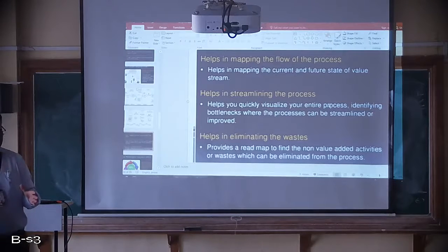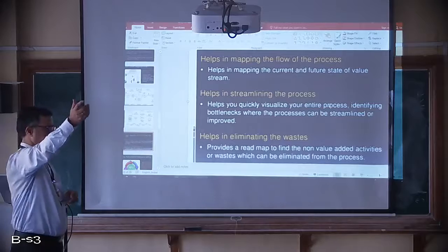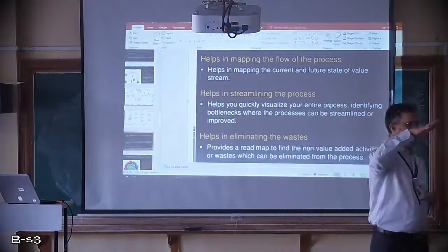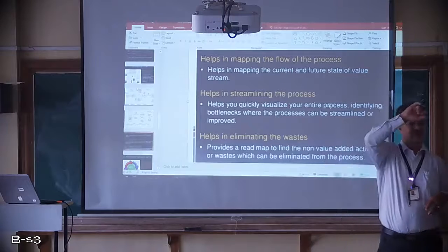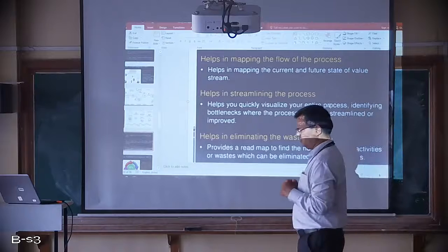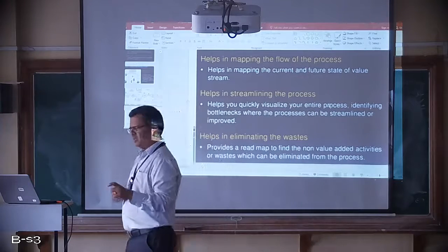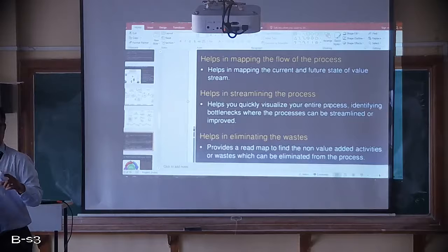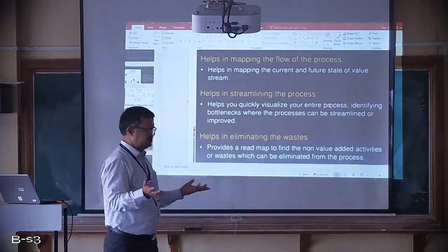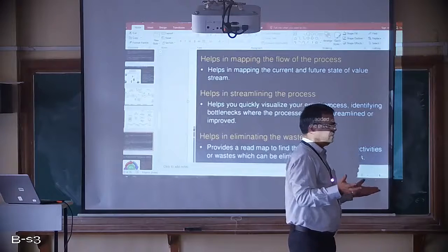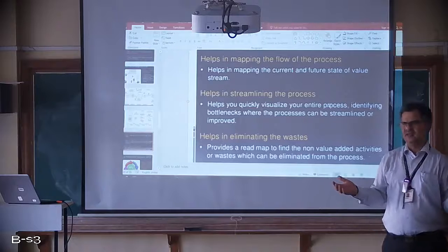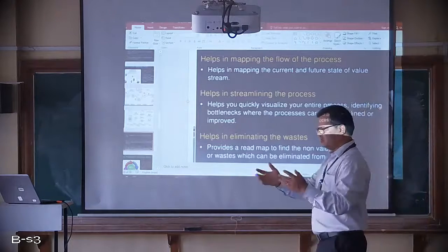Then the WIP is going somewhere else, maybe some other workstation, or maybe far away, and that operation has to be done from there only. Then it has to come back here, and then they have to start. Imagine that transporting an item to complete one operation takes 10 to 15 days outside. That is an extra 15 days of waste. When you calculate lead time, if it is around 20 days for a single product, then 15 days have gone for this only.